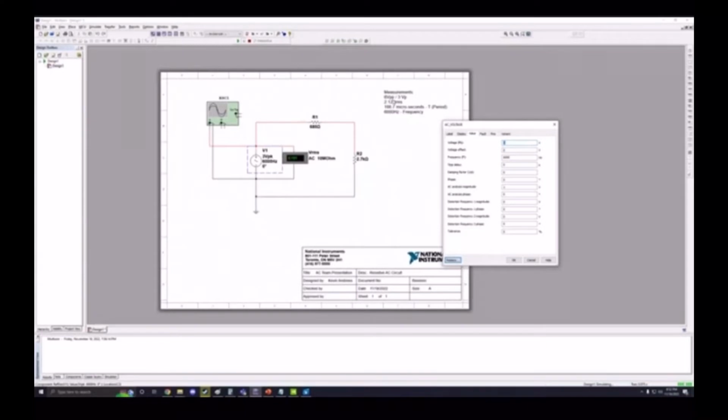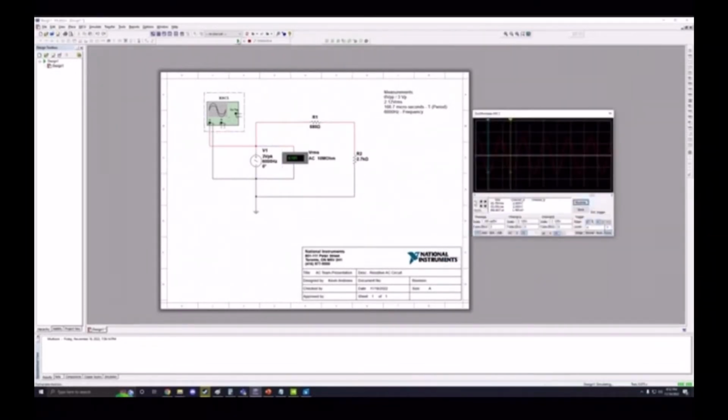To keep this brief, to measure peak-to-peak voltage, we're going to be connecting our oscilloscope in a parallel relationship. I'm going to pause our measurements just for simplicity's sake. We will be measuring with our 2 cursors. Set the number 2 cursor before the first one, as you can see, number 2 and number 1. Set the 2 to the peak and the number 1 to the valley. Number 2 goes to the Y max, number 1 goes to the Y min. And this number right here, we're getting roughly 6 volts peak to peak, which is what we're actually looking for.